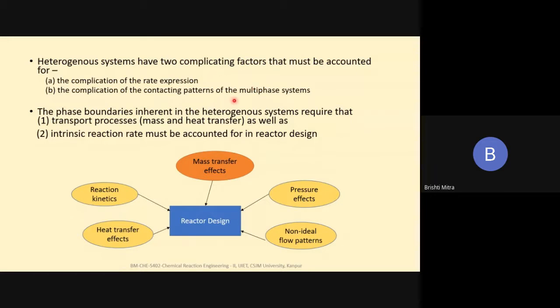The same thing happens when we have a multiphase reaction: the mass transfer from one phase to another becomes important, and that mass transfer essentially depends on the contacting pattern. How well they are contacted, what is the mode of contacting, will determine the mass transfer, which in turn will also influence my rate expression.